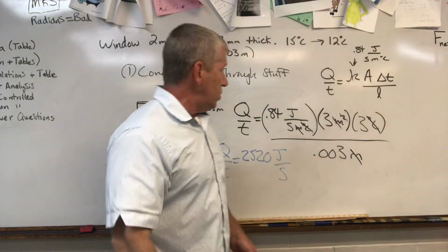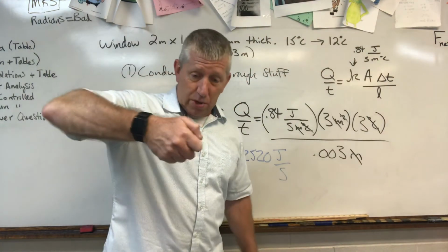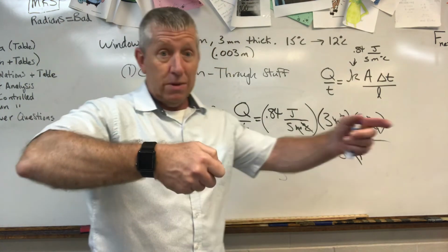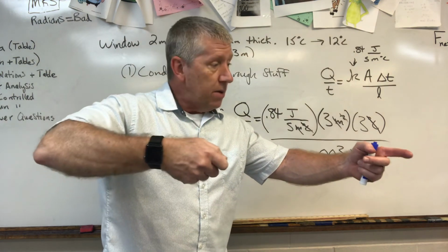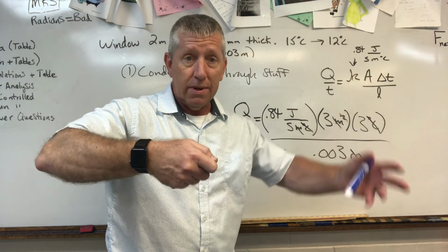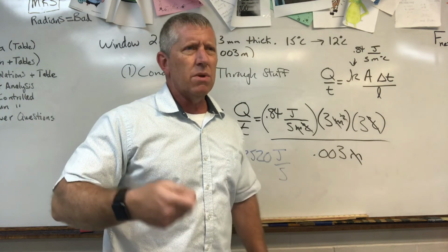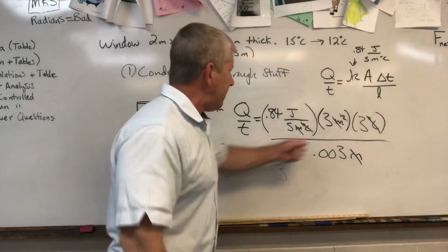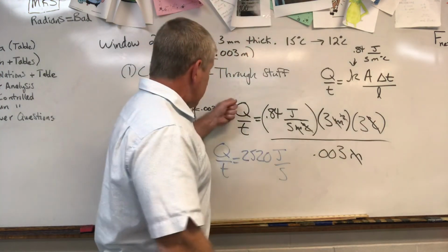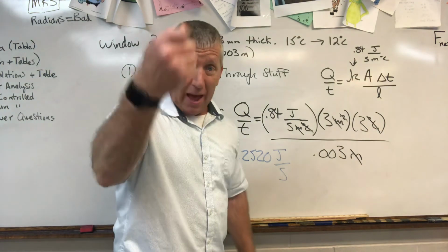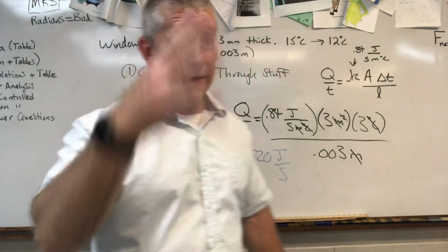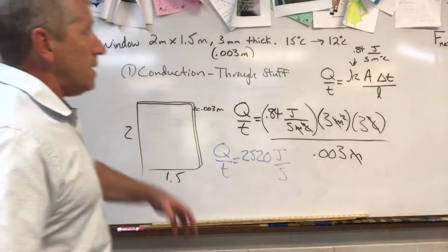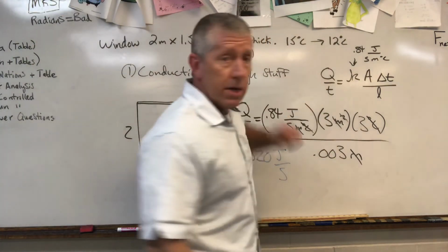So 200. And I'm warm. Okay? And the fire's a lot warmer than I am. So the fire, I don't know, 1,000 degrees, well, it wouldn't be 1,000 degrees. It was just firewood, so it would be less than that. But anyway, the point is it's a huge temperature gradient. And aluminum has a big value here, 200. You're going to get a sweet amount of flow going to that hand. And you can't hold on to it very long because of the amount of heat energy transfer. Okay, that is an example problem using the conduction equation.